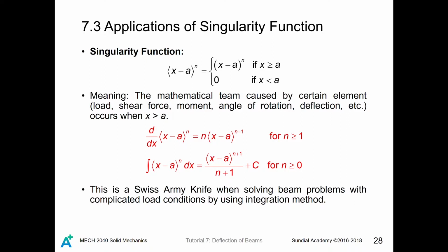So after talking about the integration method as well as the superposition method, now I'm going to introduce you to a very important function called the Singularity Function. It is very important because it can greatly simplify your analysis of the beam deflection problem when using the integration method. As my friend says, the singularity function is simply a hack for beams with a lot of load conditions.